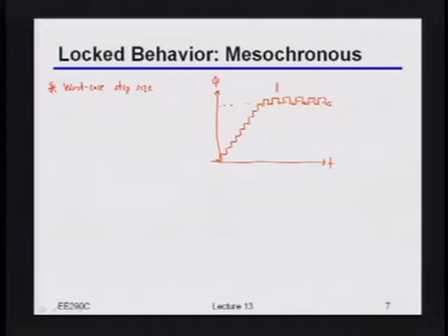But yeah. Time taken to lock? Oh, okay. So you may indeed care about how long it takes you to lock. That is indeed true. Although if I'm in a mesosynchronous system, usually I can tolerate a pretty reasonable amount of time. Because, again, in a mesosynchronous system, things are nominally at the same frequency, but I just don't exactly know what the initial phases were. So once I find that, it's a matter of catching drift types of mechanisms, right? Given that that's the case, what do you think you're going to want to do to that step size? So you're really only looking for drift.